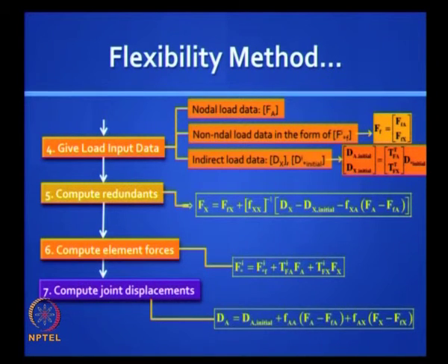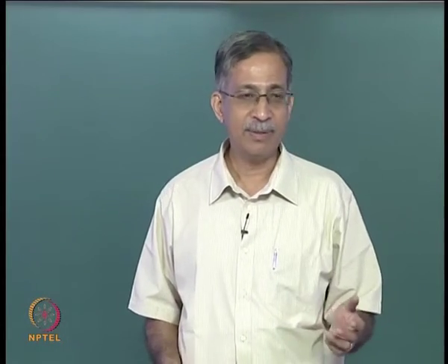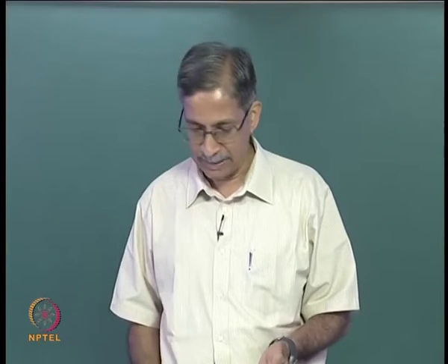In statically indeterminate structures you can compute the element forces only at the end, after you have got the redundants. In statically determinate structures you get it in the first shot itself, because you have the TF matrix complete. Let us demonstrate with the same problem, okay.